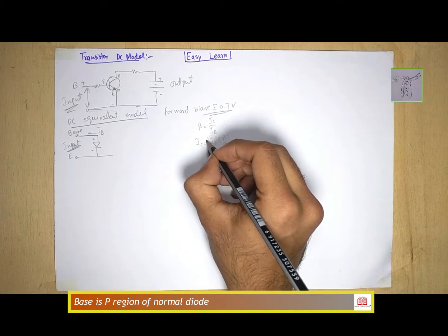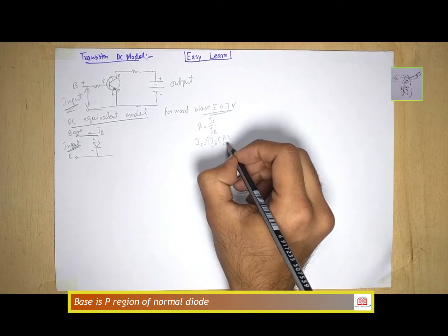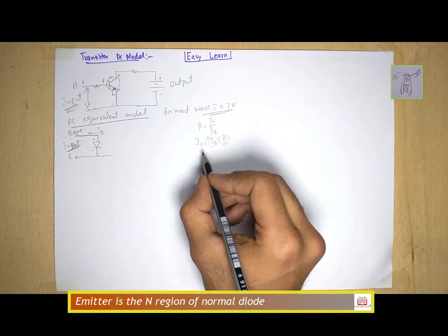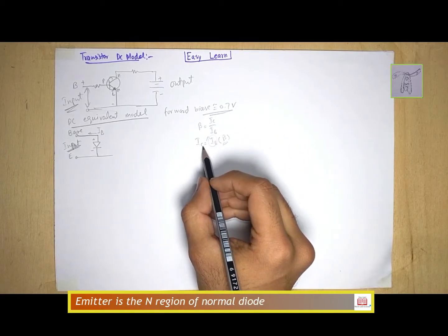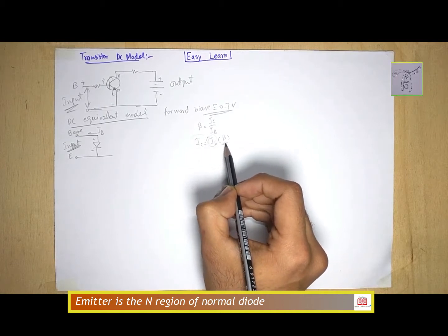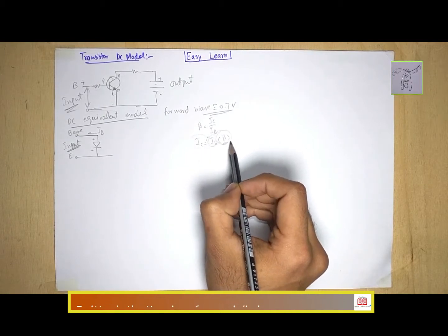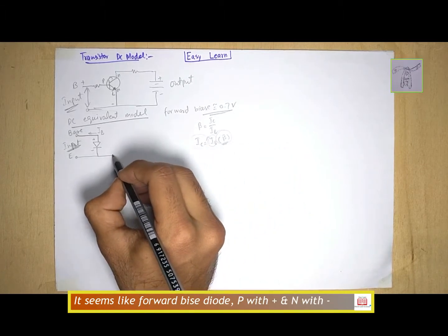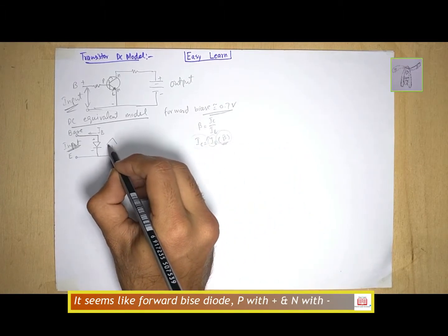If our base current is increased, it is multiplied with the gain, and we obtain the total collector current IC. So in our amplified state, the collector current is dependent on the base current IB.